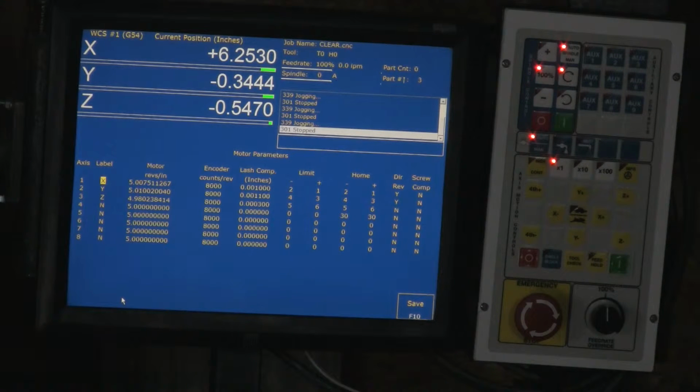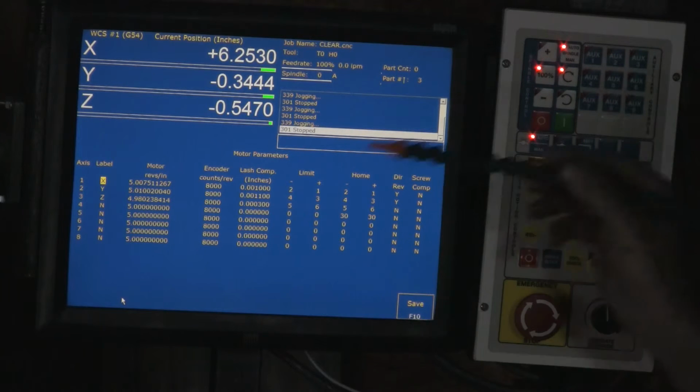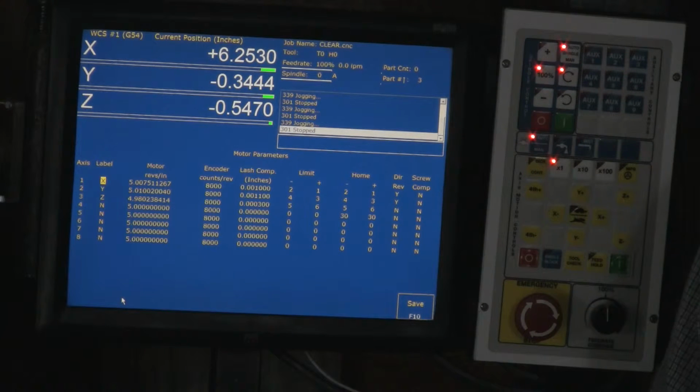If you do that, you can now go over and jog your machine and manually throw the switch. You should be able to jog the opposite direction off of it as if it were coming off the switch. That's why you want to move your table to the middle, so you have plenty of room to work while you're making sure that's functioning. Once you can trip the switch manually and jog in the opposite direction with both switches, then you know you're good to go, and you can start setting up the rest of your homing sequence.